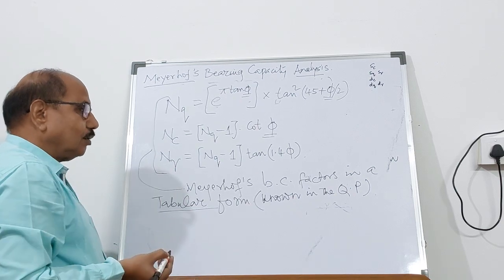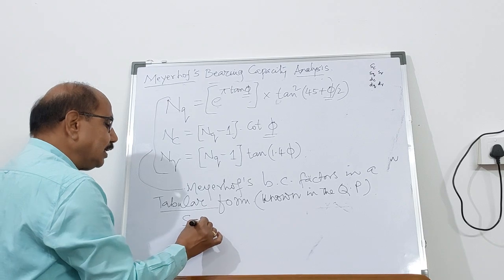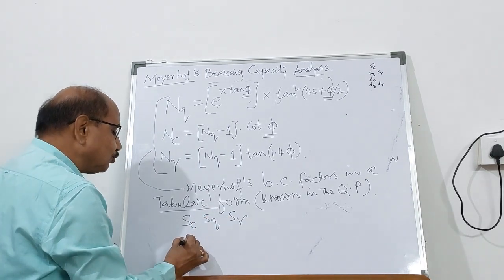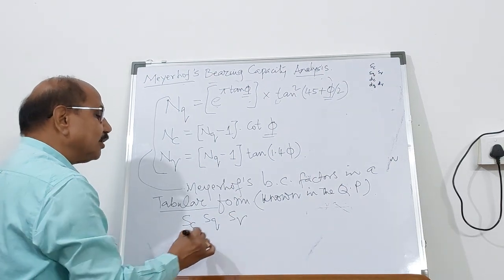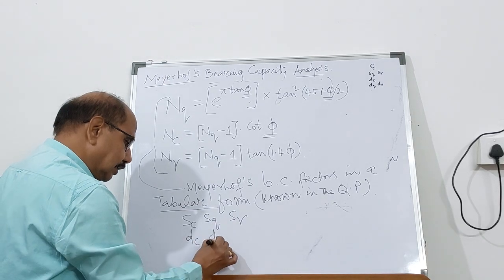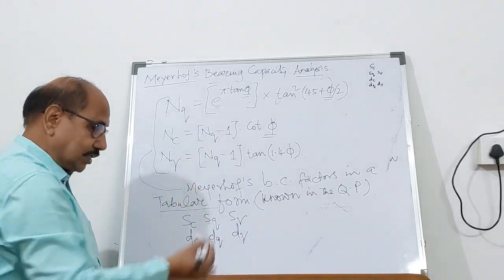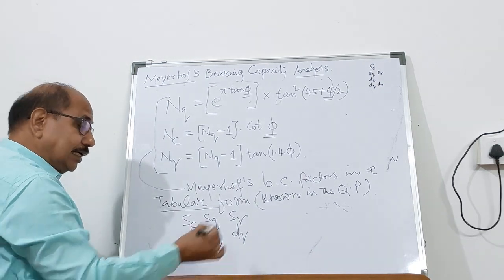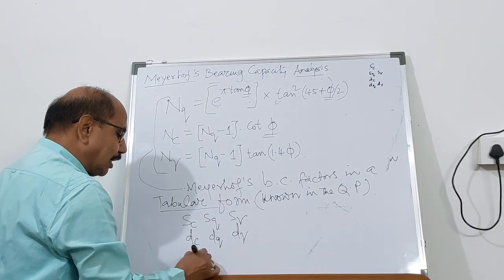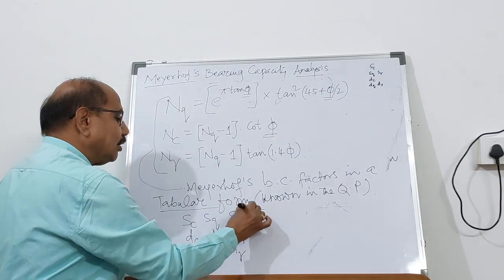But you will have to remember the shape factors s c, s q, s gamma; calculate the depth factors d c, d q, d gamma with the expressions I have given to you; and if the loading is inclined, calculate i c, i q, i gamma.